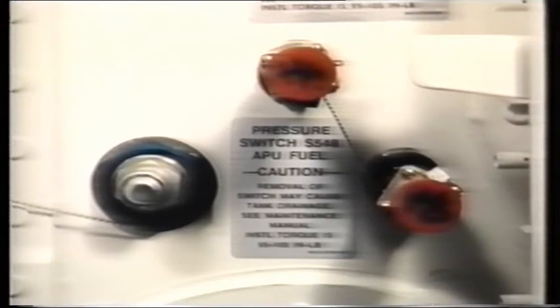The following APU fuel supply components are located on the rear spar of the number 2 main tank. The APU DC fuel boost pump, the APU fuel boost pump control pressure switch, the APU fuel shutoff valve, and the number 2 main tank aft boost pump. In review, fuel is automatically transferred from the reserve tanks and the HST. Reserve fuel flows through the valves to the inboard main tanks, and HST fuel is pumped to the center wing tank.